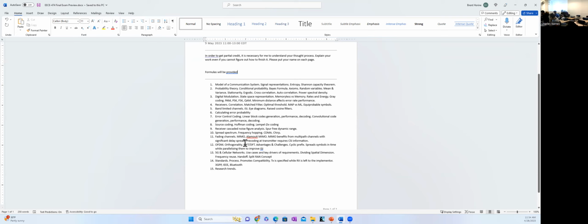As it turns out, we can easily process this using inverse discrete Fourier transforms, or the fast Fourier transform as an algorithm, at the transmitter and the discrete Fourier transform at the receiver. We'll talk a little bit more about that. We did not finish that lecture last Tuesday. And I'll talk about 5G and cellular networks today and probably spill into Tuesday.